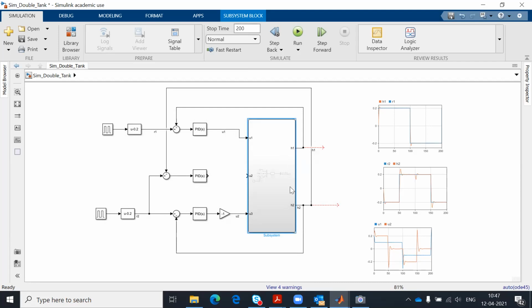But for a MIMO system, we have designed SISO controllers. If that is the case, we prefer to find inputs that have a dominant effect on the corresponding output. So this selection of inputs is quite understandable. It makes sense why we have selected U1 and U3 and why we have avoided using U2.